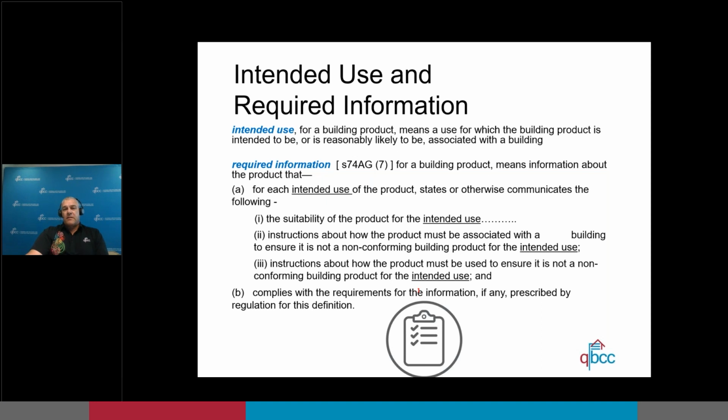What would be an example of something that you guys might be looking for as architects? If we use the firewall example that we did before, you'd be looking for the whole fire test or the regulatory information report, and most certifiers and bigger builders out there are actually looking for the whole fire test so that they can have a look at it and then compare it to the installation instructions and make sure they're the same. Remember, the fire test is the evidence of suitability that you're going to use for demonstrating that a product meets the relevant regulatory requirements.